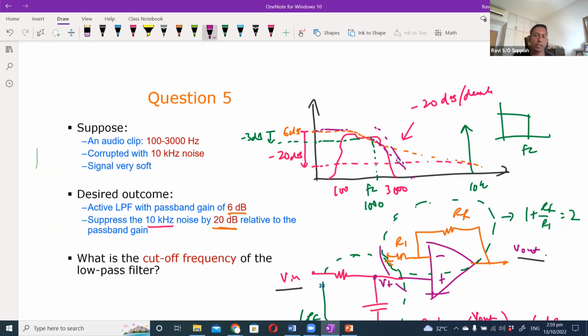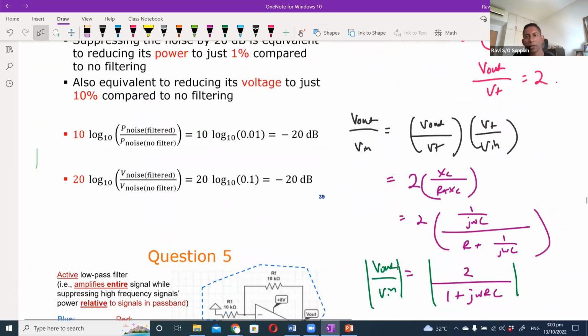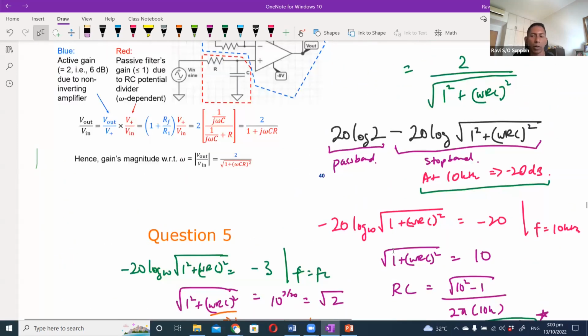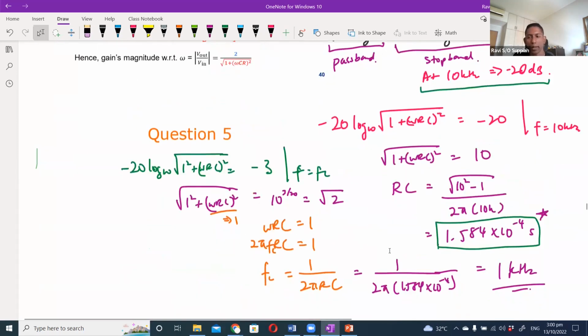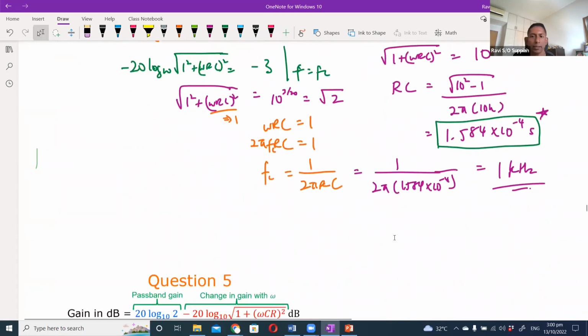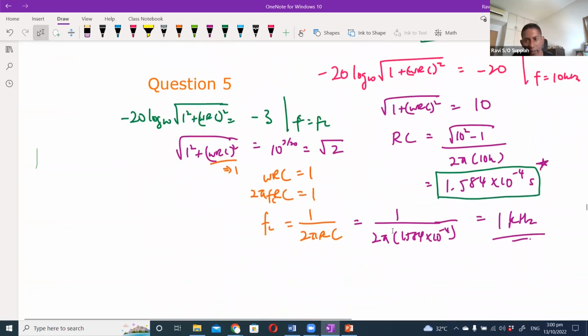Again, it is a trade-off, because when you talk about high order filters, your filter circuitry becomes more complex. So it's just a trade-off between what you're willing to sacrifice and what you want to get in the end. In this design, we achieve the objective, which is to reduce the noise. But again, the trade-off is our cutoff frequency is a bit earlier on, which means some of the audio signal also gets attenuated.